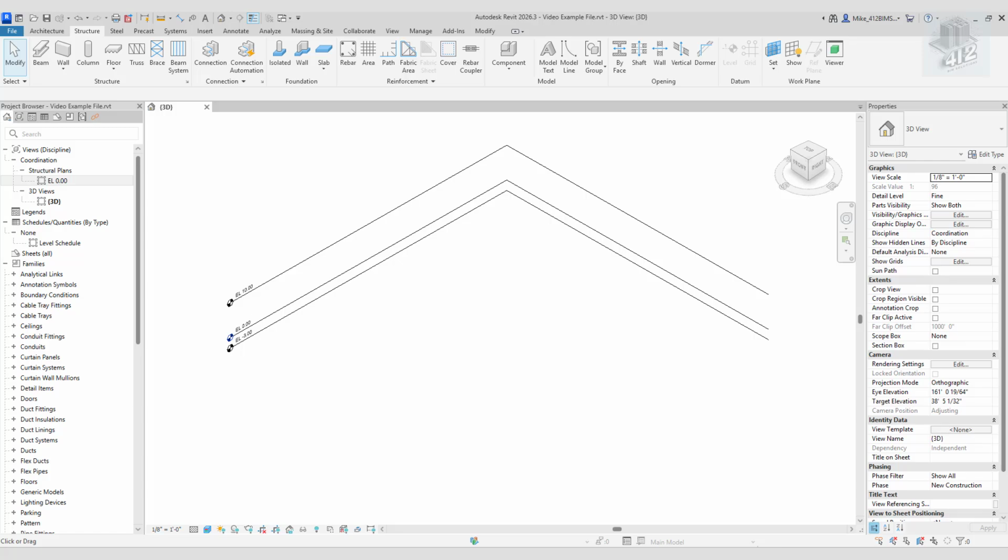Walls in Revit are system families, which means they aren't stored as standalone RFA files and can't be loaded like component families. To bring wall types into your project, you'll need to either copy-paste them from a container file where you've saved all your standards and types, or use the Transfer Project Standards tool to import them from that same file. The copy-paste method gives you some control. You can selectively bring in only the wall types you need, while with Transfer Project Standards, you get them all.